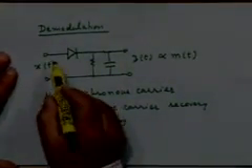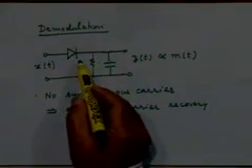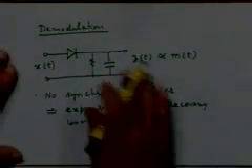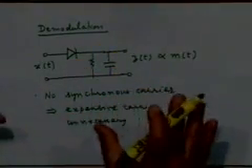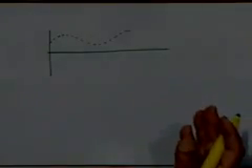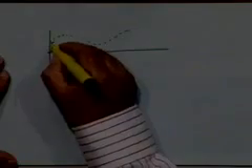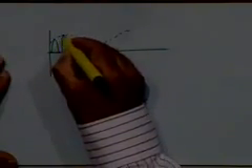Now, because the diode will conduct only when it is forward biased, you can think of this action as some kind of a rectification action, but more precisely we will see what is happening. So obviously we only need to look at the positive half cycles of the carrier wave. The negative half cycles we cannot make forward biased. So we only necessarily make it reverse biased, right? So we only need to understand what is happening during the positive half cycles of the carrier wave.